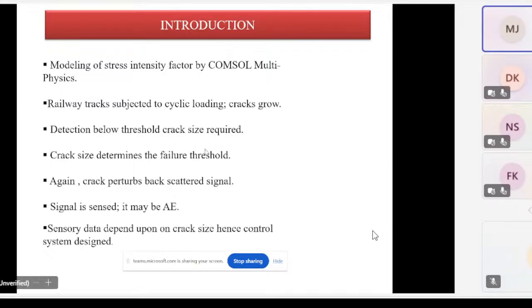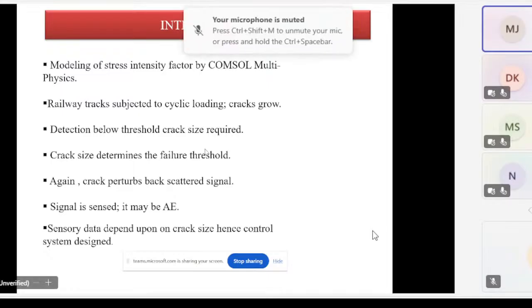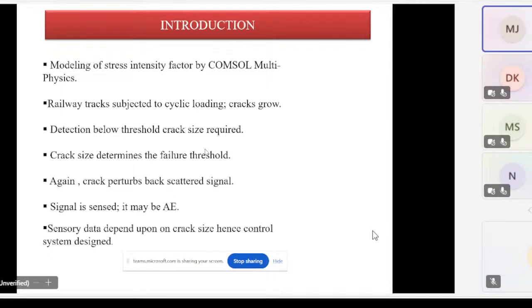So you have to understand what I'm trying to say. This is a track, the wheel is moving, and here the two pivots are there. Once it moves in here, the entire load is supported. When it goes in there, there's some bending moment. So the track gets deformed like this. There is an elastic deformation, and when the wheel passes, it recoils.